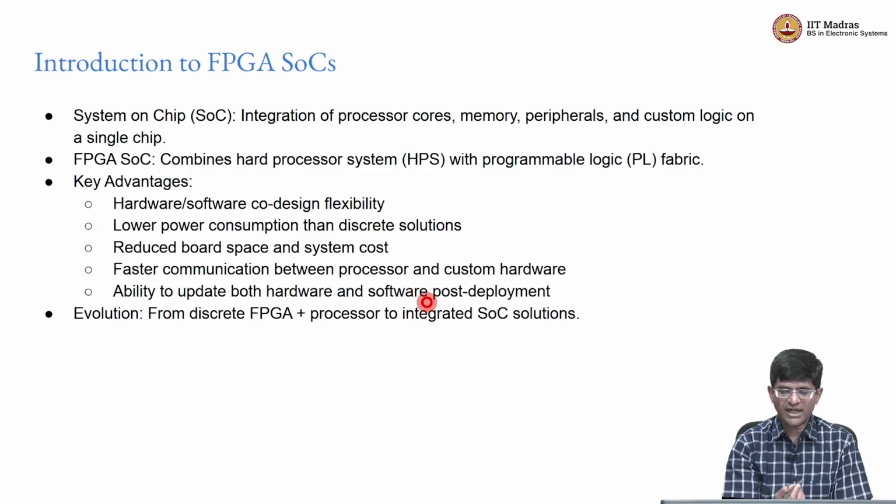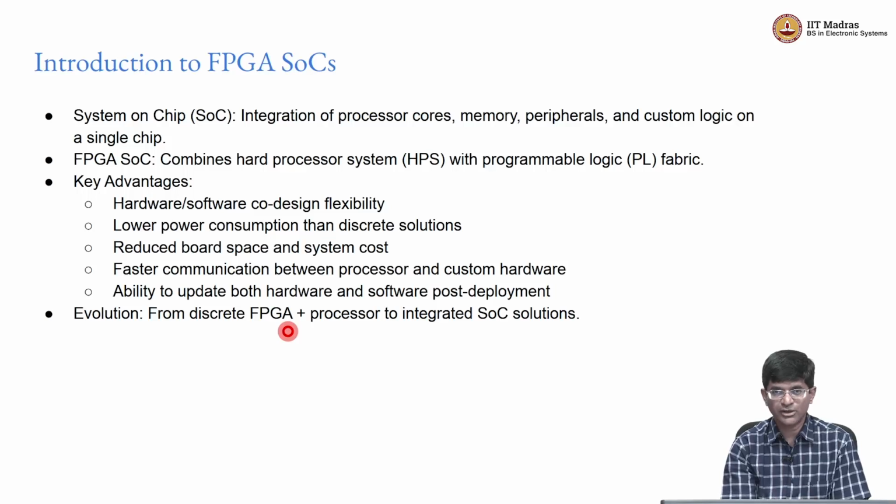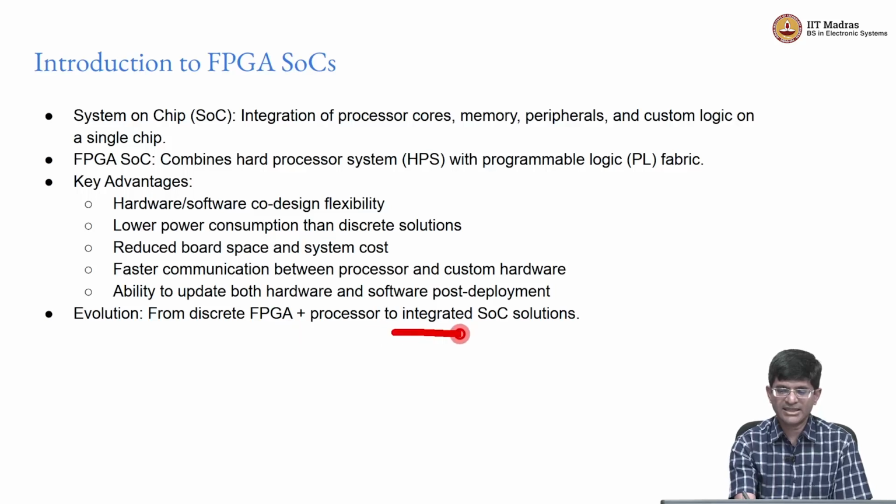So this is a natural evolution, right? FPGAs originally started off as pure programmable logic, but then eventually, as we have discussed throughout this course, you don't just work with pure digital logic at some level, you want to get programmable solutions. Programmable hardware is difficult to do, so instead can you get something which also has a software component in it, right? And that's where the integrated SoC based solutions have come in.